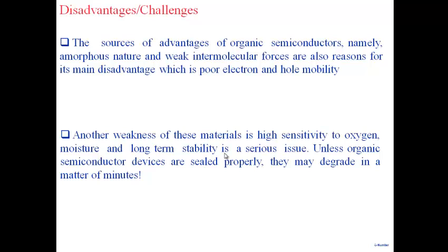And so the material is very sensitive. By the way, if you go back and read about silicon and others, they were also very sensitive. And so silicon ICs and all are encapsulated and covered, with silicon dioxide and other things. So here also, people have solved these issues to a large extent by taking an organic material and then covering it, sealing it. After you make the whole thing, you seal it so that you prevent oxygen and moisture reaching your active layer here.